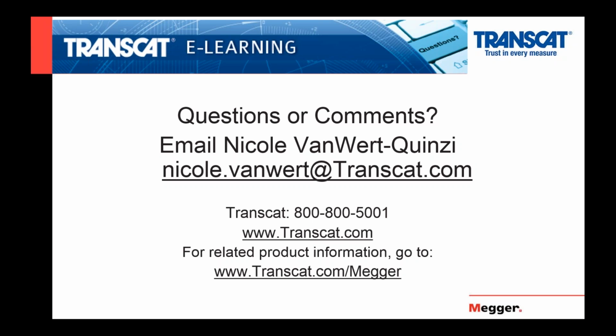Okay. Next question is, how often should we recharge rechargeable batteries when not in use in order to ensure a state of readiness? That's a very good question, because I've seen people not do that quite often. And again, I would always refer to the battery manufacturer for that, but I would never let a battery sit on a shelf for more than 3 months without topping it off and charging it up.